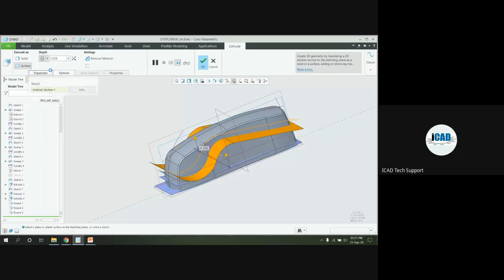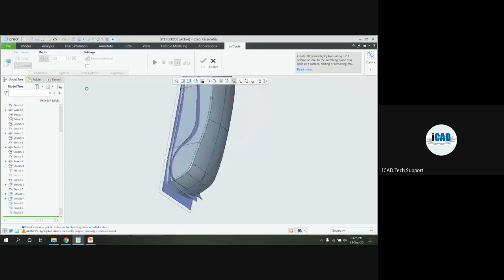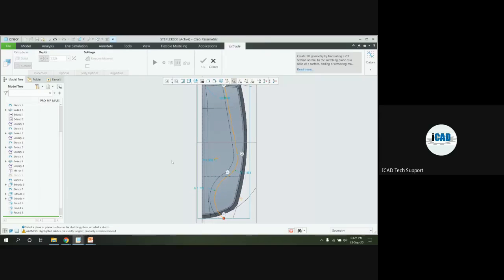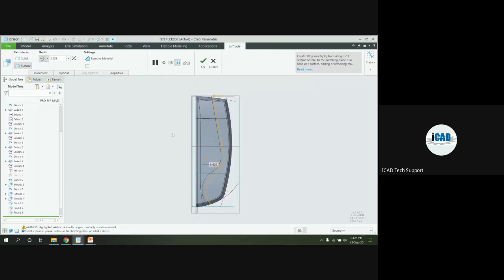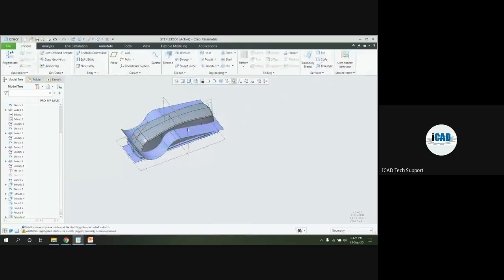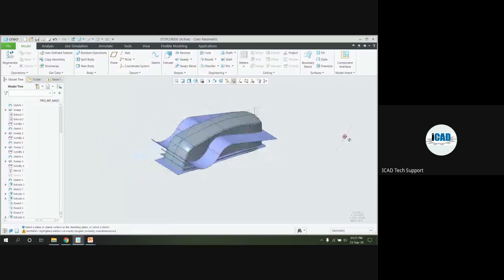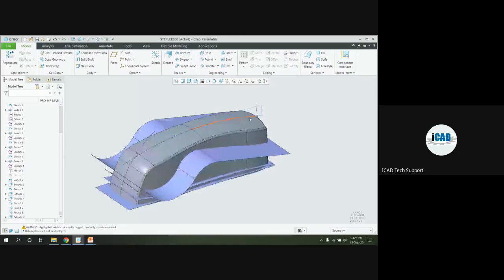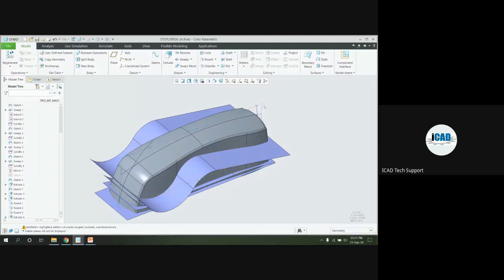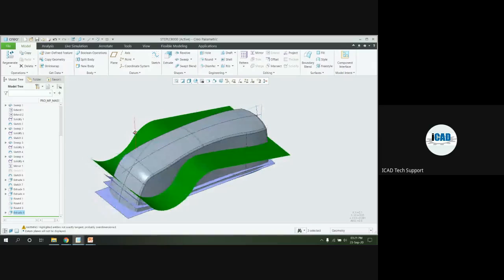And some of the options like here is the internal sketch. You can edit again if you want to edit the sketch. You can edit directly from here also. Otherwise, if I click on the OK button, you can see the surface gets created. In Creo Parametric surfaces, whatever surface modeling you are doing, a special sky blue color will appear, and by using this, you can understand what surfaces we can create. You can also change the colors for it.